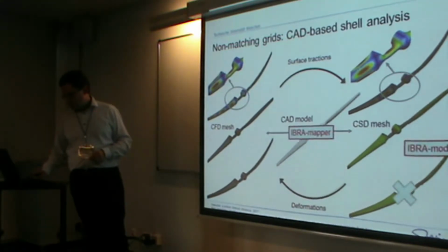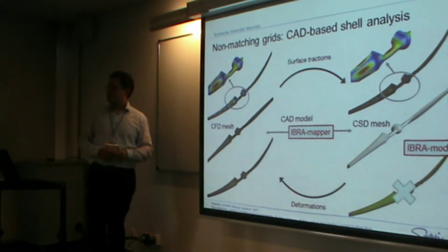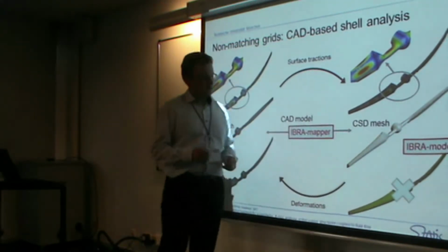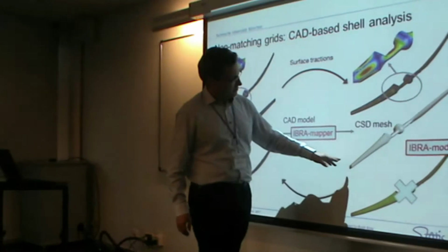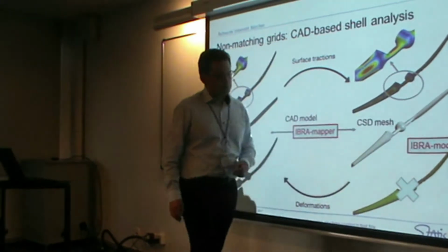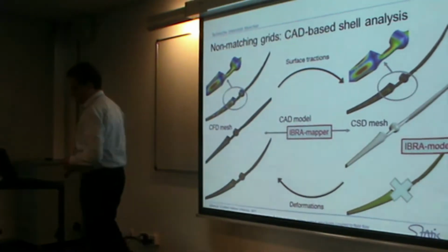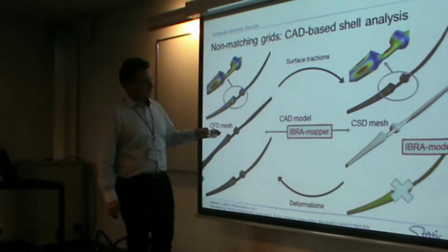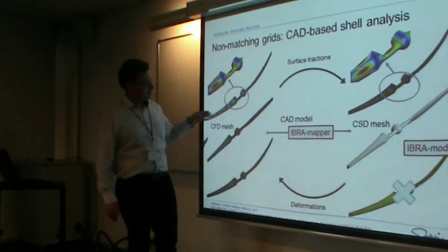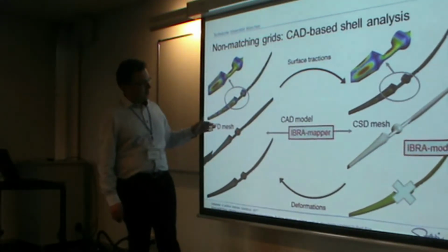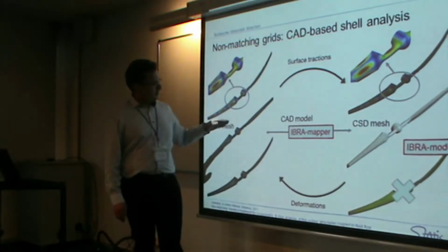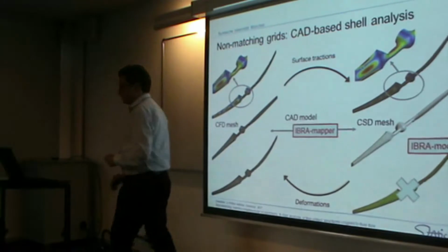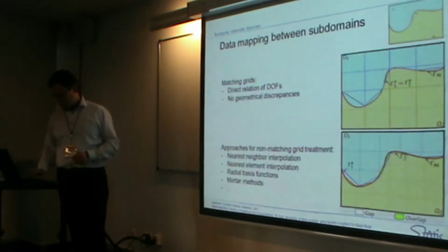We can go and say we do the simulation directly on the CAD models. What we have now resolved, the first step was with Robert Schmidt with the trimming operation, but now with Michael Breitenberger's work we are actually able to compute directly on these shells. So the question is, how does this work? Having CFD meshes, all different facets, so we have OpenFOAM, we have Kratos Multiphysics, and we will see later on body fitted and embedded would be the wish list then, coupling that directly to the isogeometric B-Rep simulations.